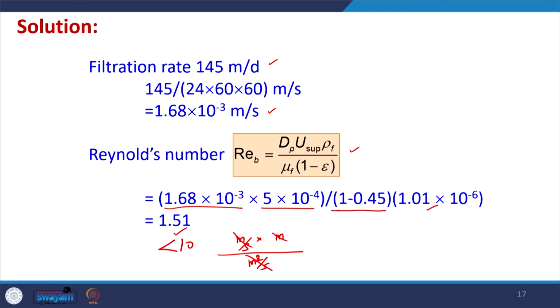If we are using sand itself, epsilon will be fixed, so we can modify the superficial velocity a little bit. Through this we can modify the cross-sectional area and vary the diameter of the bed, and that becomes a design condition.